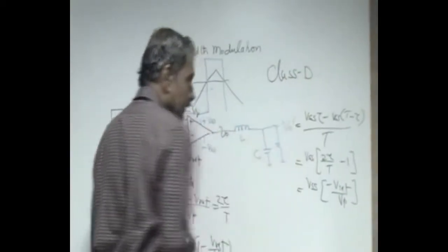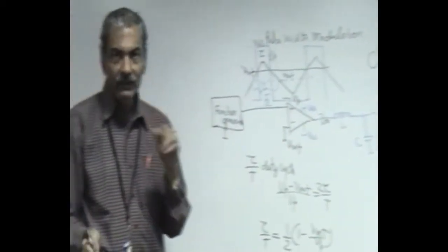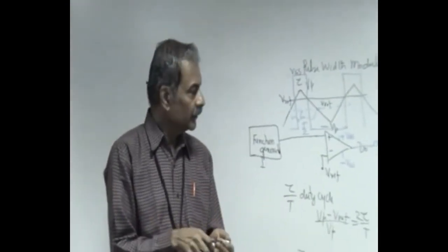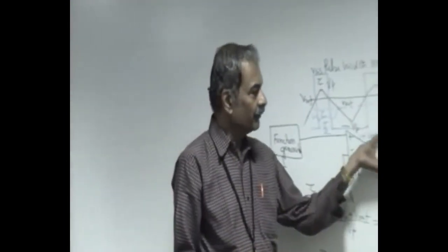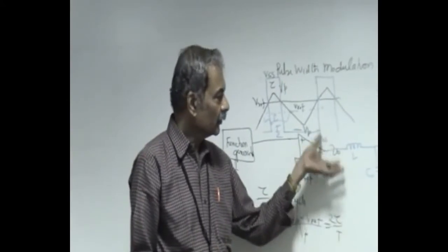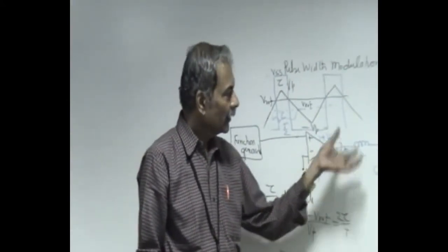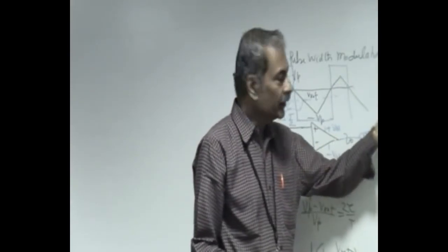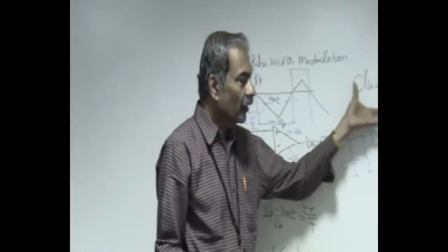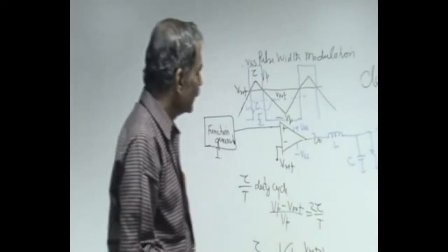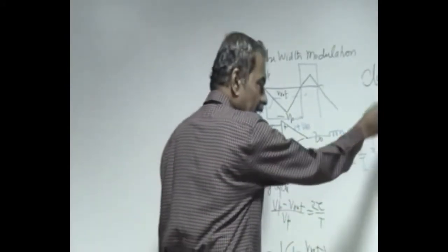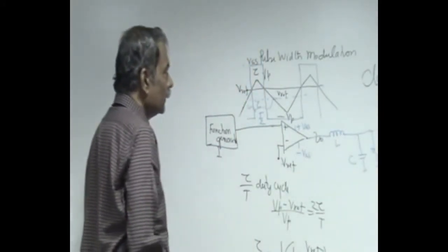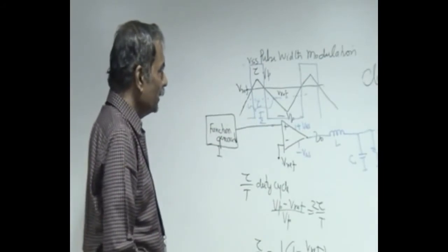D power amplifier stage. And presently you will see that all audio stages make use of a MOSFET or something else as the switching device, and the information can be efficiently converted at high power level into audio power at the output. It can directly activate the speaker, and that is one application.